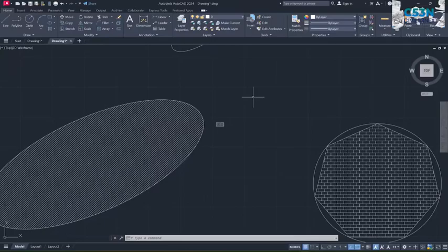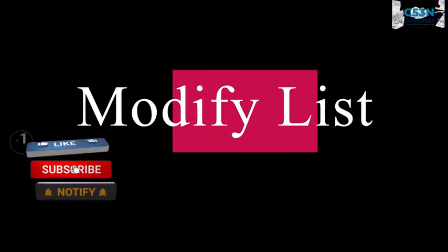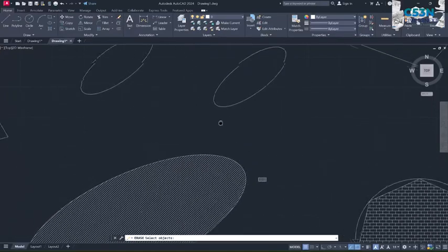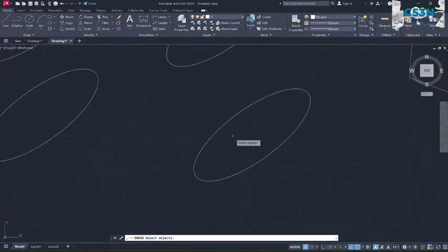The seventh command we will be talking about is erase. To select, left click. So let's say that you want to remove this object. By moving my cursor on the object, as you can see, it becomes like X and it becomes lighter. So left click. Now to confirm selection, right click.